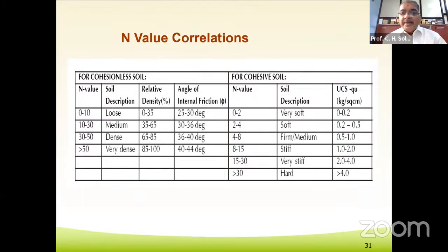In the last slide, I presented that 85 to 90% of the foundation design is on the basis of the N value. These are used to find out the safe bearing capacity of the soil or the ultimate bearing capacity of the soil, and that's why these parameters can be used for that purpose. Hence, this slide has been presented.